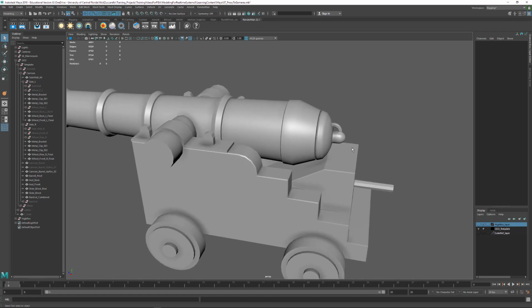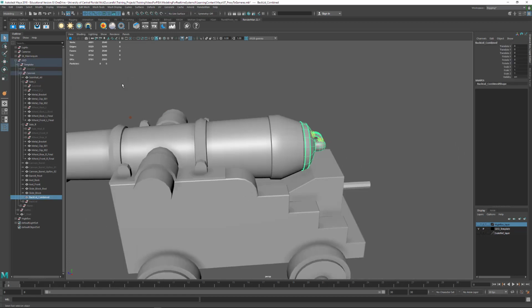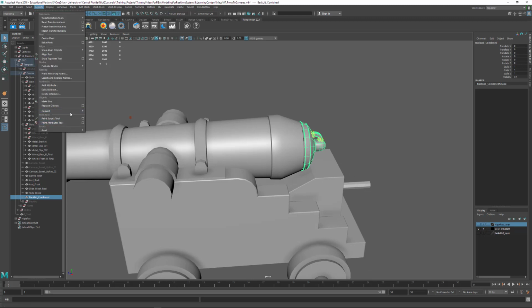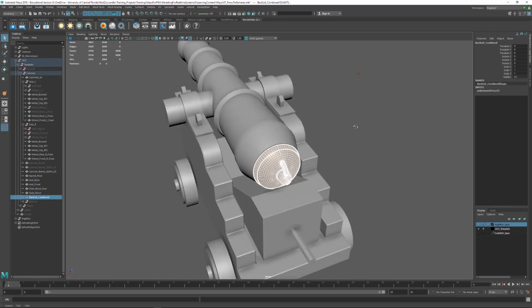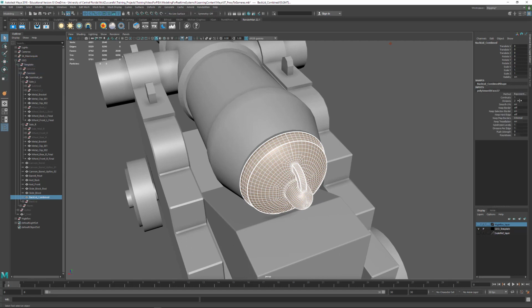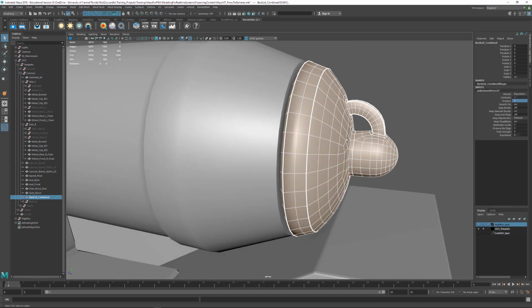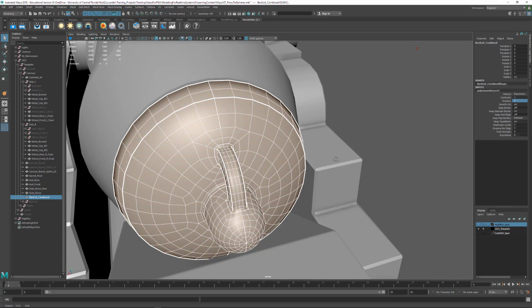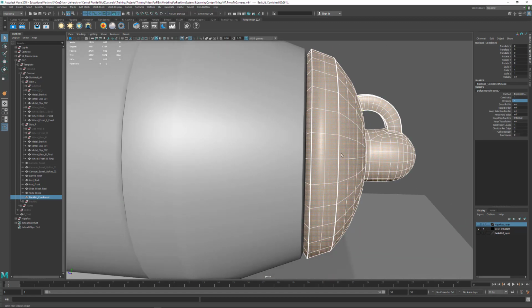and I'll hit Control 1, and you can see, if you remember from the earlier stages what we did, we took this right here and then went and did a modify. So we go to modify, and then we convert smooth mesh preview to polygons, and that's a pretty high resolution model. Put that down to 1, and then it's going to be a matter of going through and maybe reducing some of the pieces that are within here that we don't need.